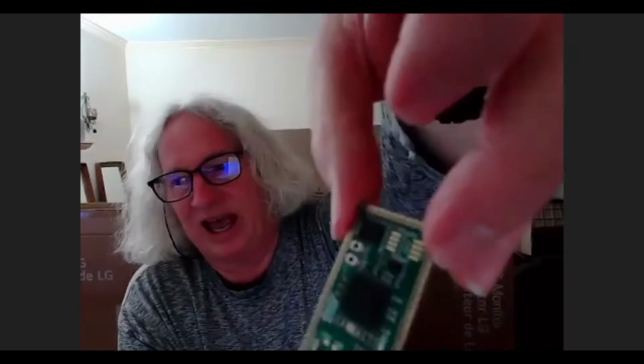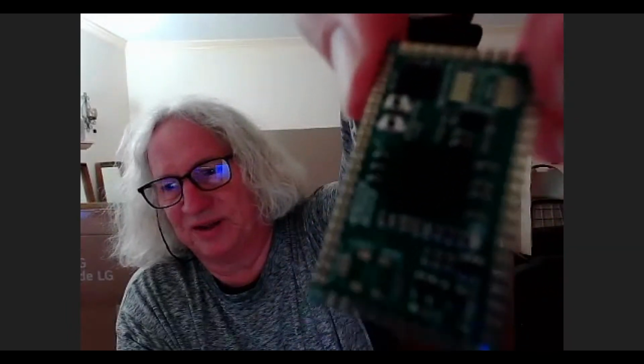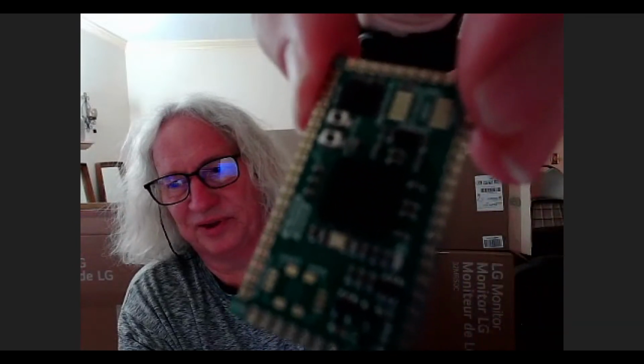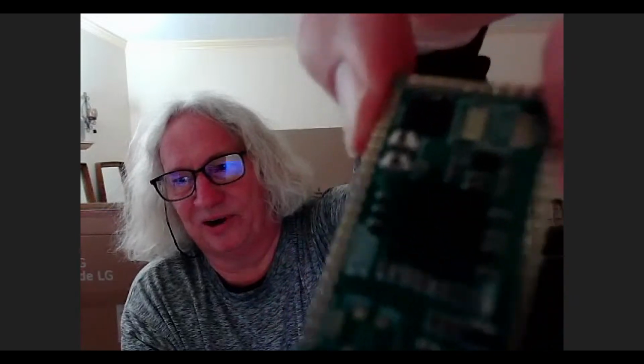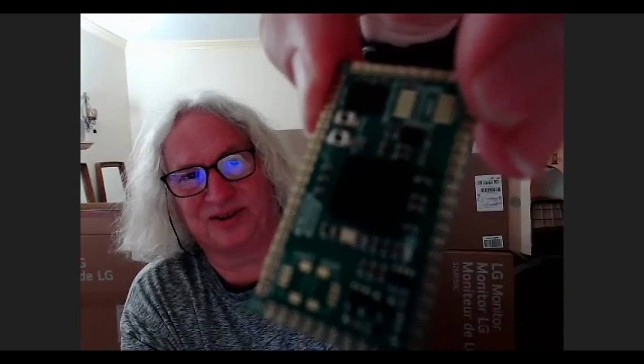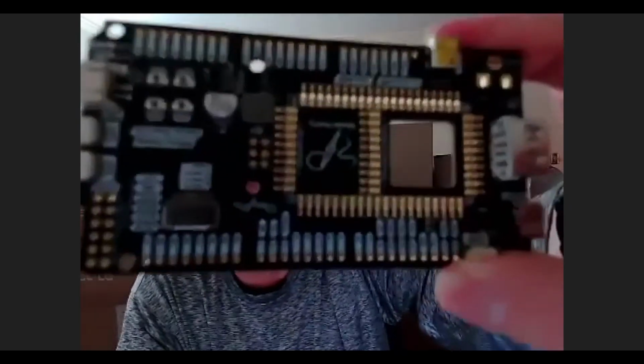And there are newer versions of the Pi Pico coming out. And this one's really interesting. This is the Stamp XL. It's got the 2350, the new version of the microcontroller, but it's on a board that's able to output all 38 or 40 GPIO lines by doing the top and the bottom as well as the edges. When these are more available, it's going to be really interesting. Right now, they keep running out of them, and that's a developer board to put that XL stamp on. So that's a hint of future things.